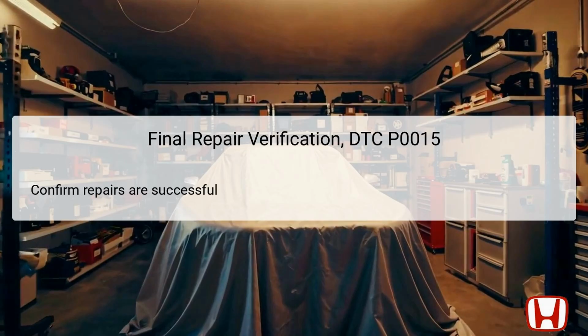After conducting all the necessary inspections and repairs related to DTC P0015, it is crucial to verify that the repairs have resolved the issue. Start the vehicle again and allow it to reach its operating temperature. Observe the engine closely for any signs of returning symptoms associated with the DTC.